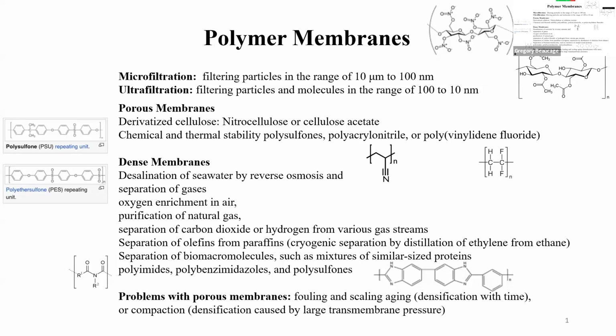Yet the gas streams from natural gas have different markets. So ethylene is going to be used to make polyethylene, ethane is a chemical precursor, or you can burn it. Or you can put it through a process to dehydrogenate it to make ethylene from ethane. Right, but basically, in the chemical industry, you want to separate those two, and they're exactly the same molecular size, and they have the same hydrophobicity. So the only way to do it is you can use membranes, membrane separation.